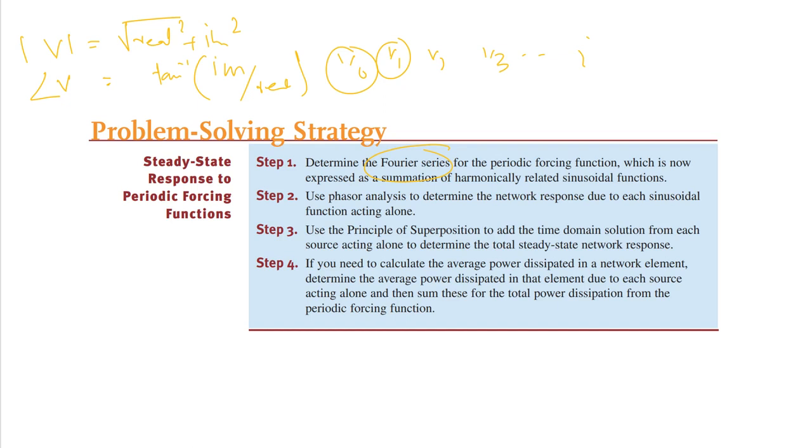So we multiply, let's say, I of 60 with V of 60, not the other ones, and then we add up all things. So I of 0, V of 0 plus I of 60, V of 60 will give us the power of these sources combined.